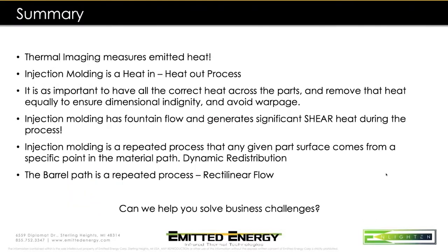Okay, so what do I got? In summary, we know that thermal imaging measures emitted heat, as Roy gave you a pretty good introduction to. That injection molding is a heat in, heat out process, and how much you put in and how quickly and consistently you take that heat out. The consistency of that heat is important. We have to have all these parts correct, and we have to have them for dimensional integrity, and to avoid warpage, and to have the aesthetics that we're looking for.